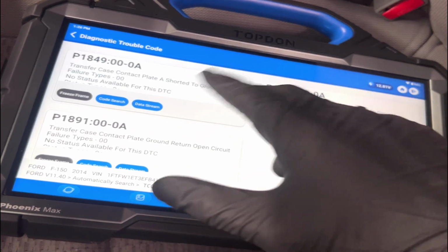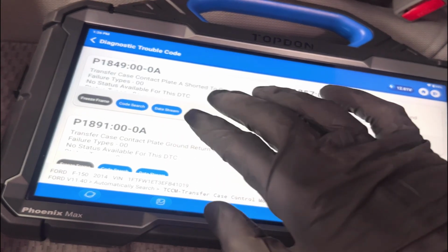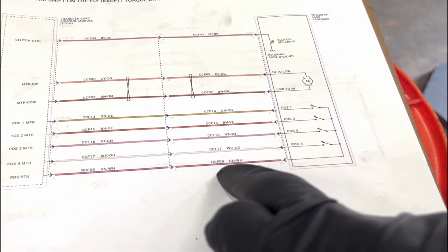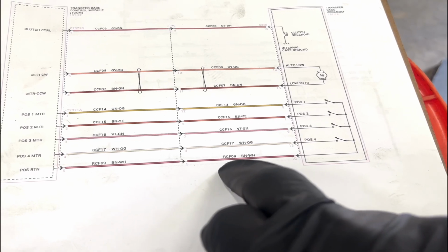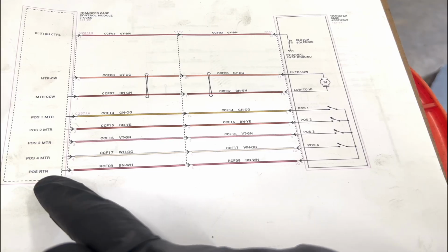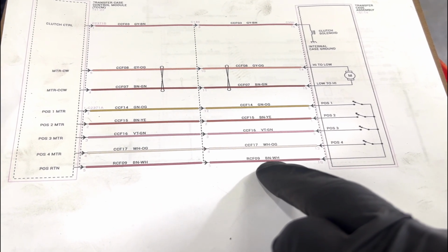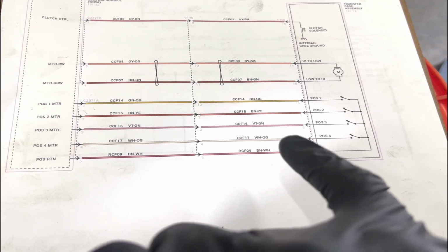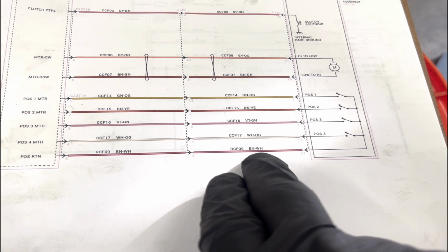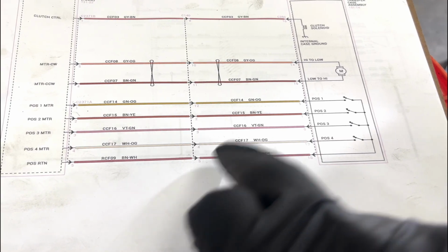With the test light in there and some of the switches closed, these 3 codes keep coming back no matter what I do. In this moment, we do not know if that 12 volts is coming, well, it has to be coming from here, you would think. So let's go ahead and unplug this connector with the scope installed and see what our voltage is on this wire. Because what we're probably going to have to do is see, because I'm questioning, when we ran this to ground, these switches, are going to, see, this is what's weird.